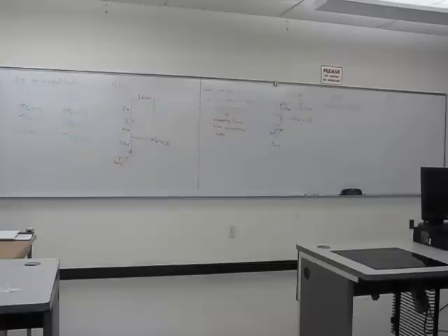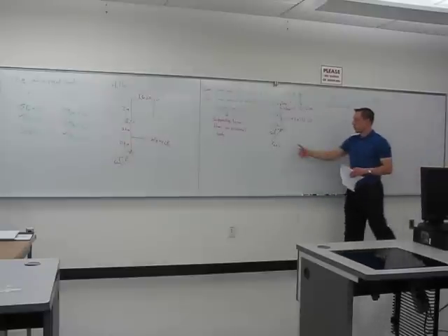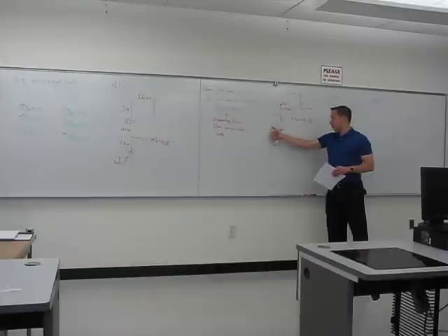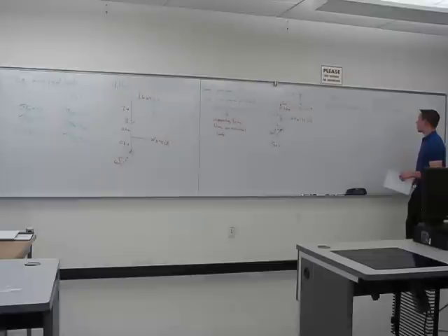Well, that equation has 2 unknowns. Fa is unknown, Fcx is unknown. So right now, I really can't do anything with that equation. So I'm going to have to write another equation and see what happens. Let's take the sum of the forces in the y direction. So in the y direction, I have a component for Fa that is vertical. Your components here, you go up for the y and you go to the right for x. So that's why we had positive Fa here. And we'll have positive Fa, but now sine of 60, plus Fcy minus Fd equal to 0.